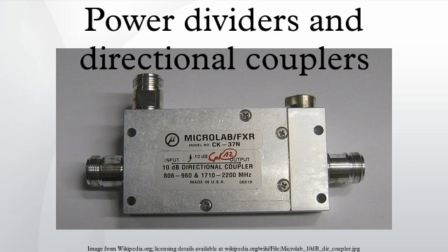The term hybrid coupler originally applied to 3 dB coupled line directional couplers, that is, directional couplers in which the 2 outputs are each half the input power. This synonymously meant a quadrature 3 dB coupler with outputs 90° out of phase. Now any matched 4-port with isolated arms and equal power division is called a hybrid or hybrid coupler. Other types can have different phase relationships. If 90°, it is a 90° hybrid, if 180°, a 180° hybrid, and so on. In this article, hybrid coupler without qualification means a coupled line hybrid.